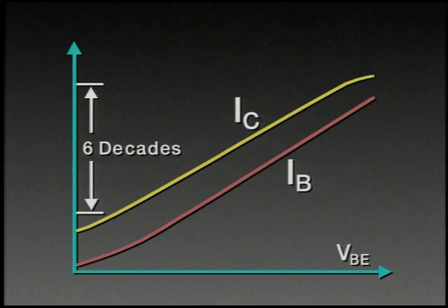So the base current is shown here, and of course the ratio of those two currents is the transistor beta. As you can see in this particular pair of curves, it's the distance between the two lines, which on a logarithmic scale represents the ratio of the currents, is constant until very high currents when the beta begins to fall, and at very low currents when it falls again.